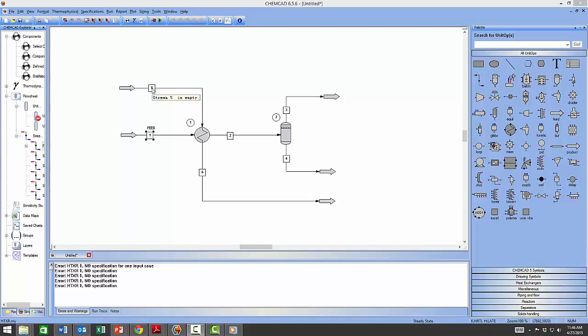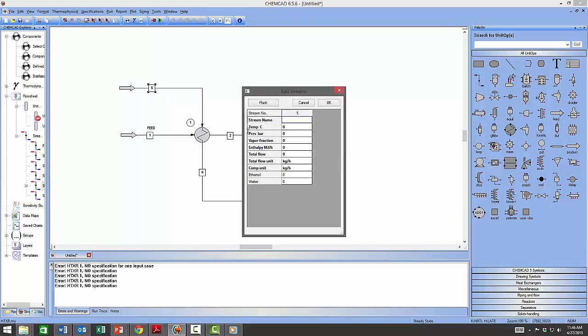We can further specify the pressure of the cooling water to be whatever pressure that you feel your design can handle. Let us start with the temperature here, which is 30 degrees Celsius. The pressure, for simplicity, we will go with the pressure similar to the process pressure, which is 3.5 bar absolute.